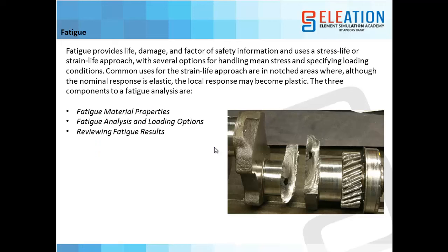One more thing which we are going to see is fatigue analysis, where we see the life of the component, that is, how many cycles it will work. So this cycle means that for one loading cycle or entire data that it withstands, we create some set of loadings, we consider that set of loadings as one cycle, and we calculate the number of cycles, that is, the number of loading sequences for which my component will withstand.